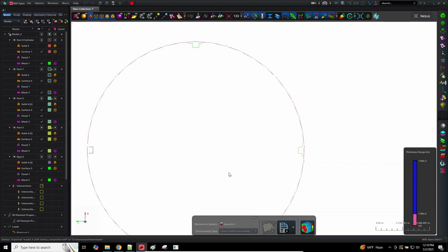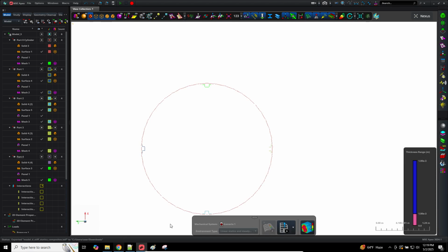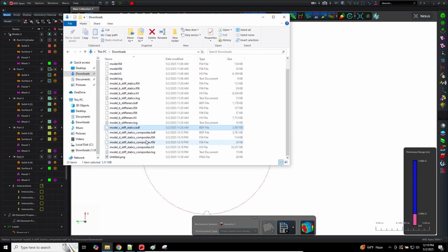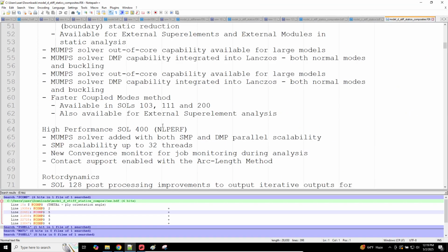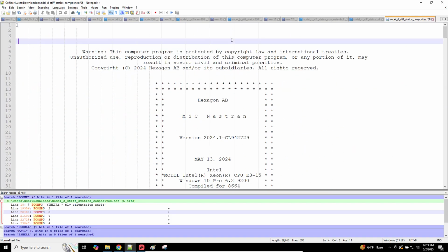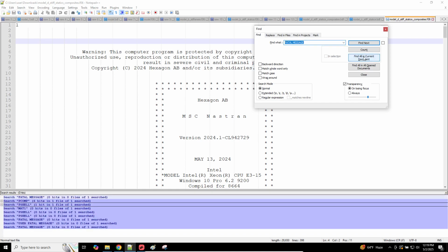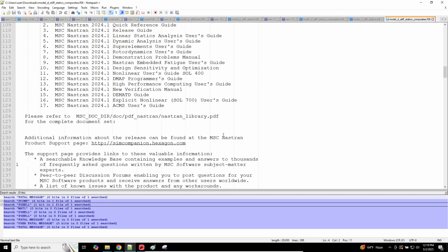Okay, so let's start wrapping this up. Let me see if I can do this. Or actually, I'm not. Let me do this. Okay. We're almost done with this exercise. Okay, perfect. So let's open this F06 file. Let's look for any fatal messages. If you ever see a fatal message, your analysis has failed, there's a problem, find that error, read that error, fix the error, try again. Okay, now there are no fatal messages here.